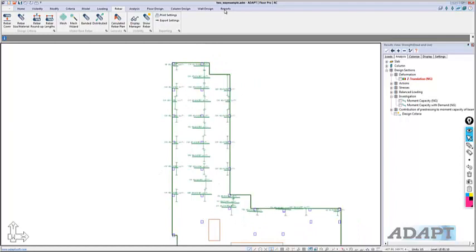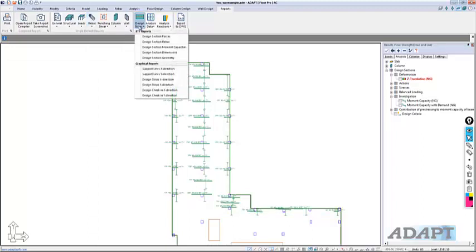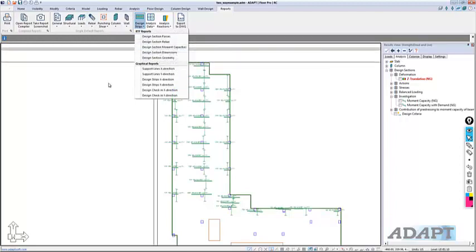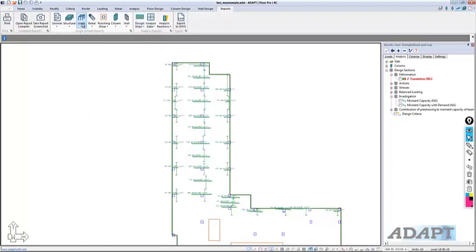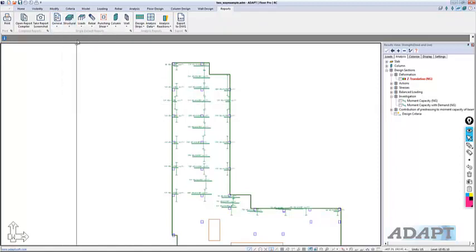If you go to the reports menu, you can then generate reports for rebar that's generated from the structural model. You can go to design strips to look at design section forces, reinforcement, moment capacities, and so on. And then there's other reports for just basic general information, structural modeling reports, loading, punching shear we have not looked at.